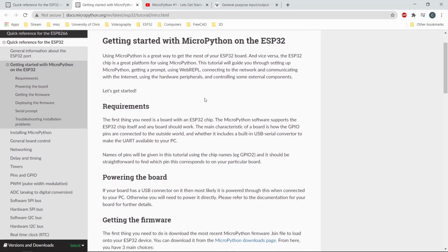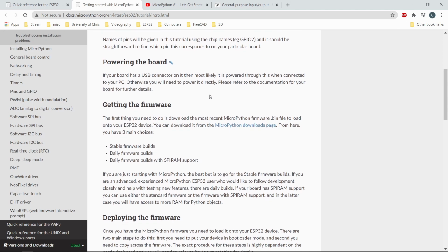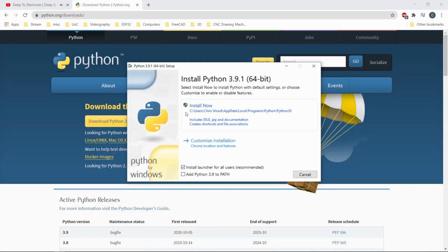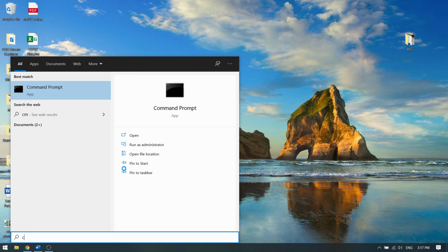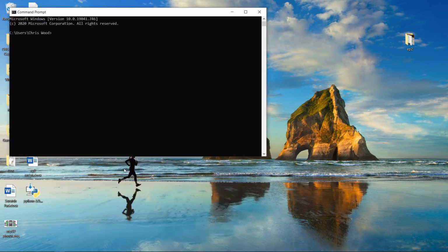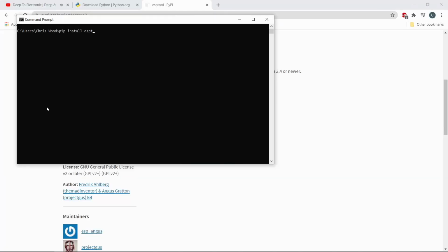The next step is to take our microcontroller, erase whatever junk it came with from the factory, then load it up with MicroPython. For this, we are going to use some tools that came with Python, and we're going to do it in the Windows command prompt. This part's exciting, makes me feel like a real computer person. Hit the Windows key, type CMD, hit enter, and you are now in the command prompt. Remember earlier when we were installing Python and we selected Add to Path? Here's where that comes into play. Since the Python commands are in the path, we can simply type in Python commands and Windows will figure it out. If Python was not added to path, we would have to do a lot more typing.